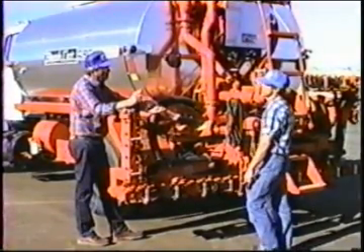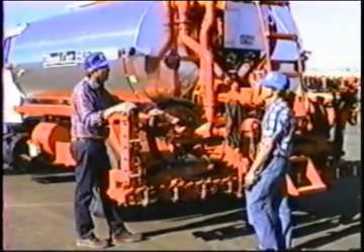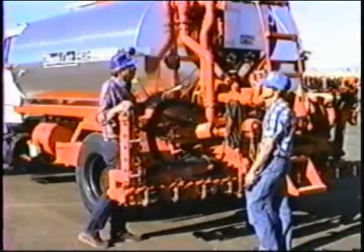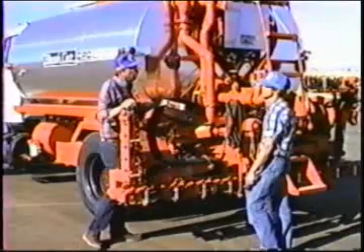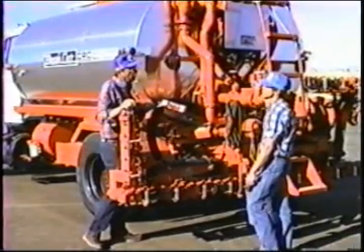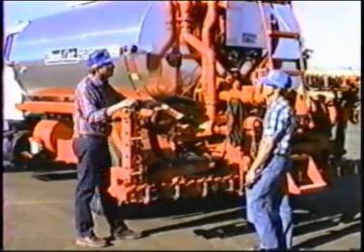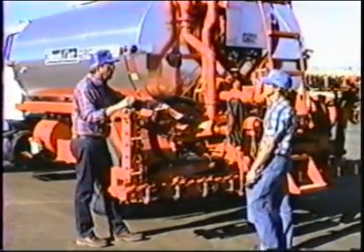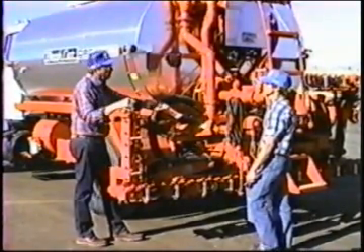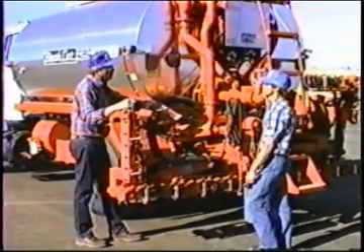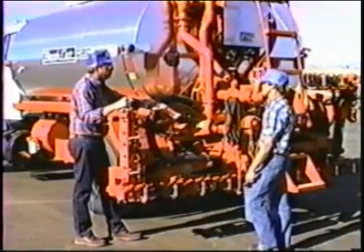You can change it. You can even make that change while you're spreading. That is, if you're going along putting down 0.25 gallon to the square yard and the road engineer told you that he wants to up the rate to 0.35 gallon per square yard when you get to the shady areas, and that's fairly common when you get back east. They like to see a little bit more asphalt on the shady areas. As you got to that area, you could just hold the computer up to where it read 0.35, shoot through the shade, and when you come to the other end, hold it down until it reads 0.25. You can make any of those changes while you are spraying with the machine.